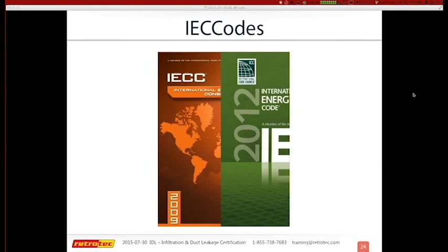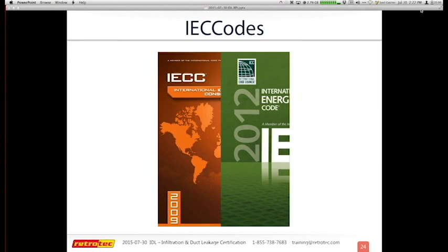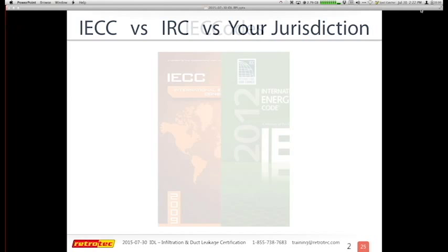All right, and we will close it, and I'll show you what we got. There's a fair amount of people that are clearly on the 2012 and doing both. So if you could help us out with what your duct testing requirements are, at this point you should be around 4%, or 4 CFM per 100 square feet, or your blower door, which for many people is going to be 3, which actually is a pretty shocking number. All right, I'll hide those, and back to codes.